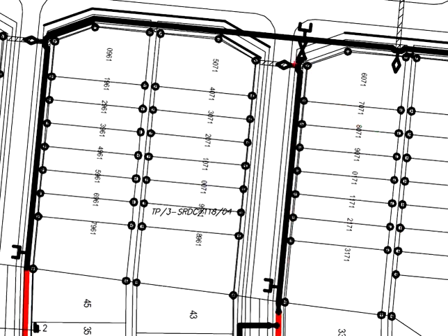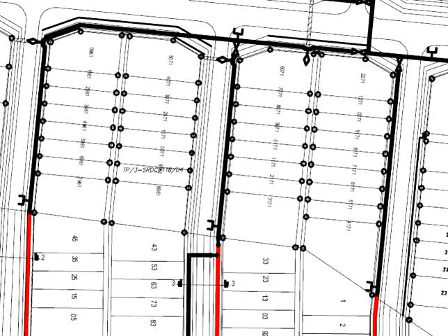Now, what makes the difference between having the loop here and having an individual water reticulation system here? The independent water reticulation system here will have to be of equivalent size to the others. Whereas, if you are using a loop system here, you can choose a smaller size main, and share the water that can be supplied into those units. These are some considerations related to the water reticulation systems.